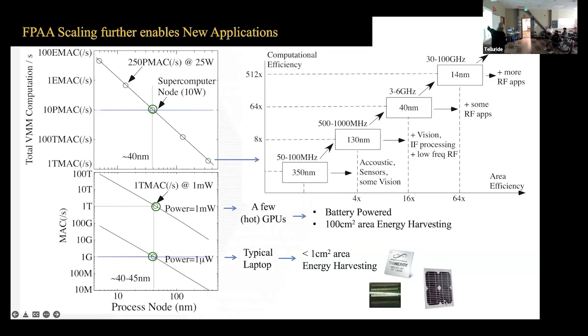But yeah, as you get to higher and higher process nodes, you can definitely do some very interesting things. Obviously the computing numbers are interesting, but I particularly love the efficiency numbers of what you could potentially do on a single chip. And I can tell you exactly how to expect these numbers on an FPAA type of configurable device. A lot of what buys us this is that we can do a lot of the computing through the routing infrastructure itself.